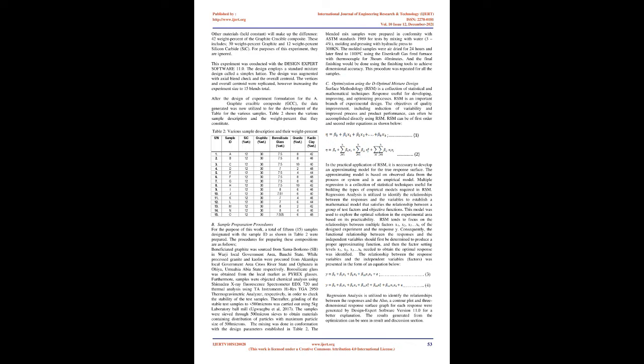6. Patent presented invention on graphite article. The invention tried to improve binder for graphite. The work highlighted the methods that the improved binder can be prepared so that the properties of the graphite paste are improved as well. The binder consists of liquid coal tar and acts as hardening agent as the binder is heated together with graphite. The preferred ratio of binder to graphite is of about 25% tar by weight and 75% graphite.